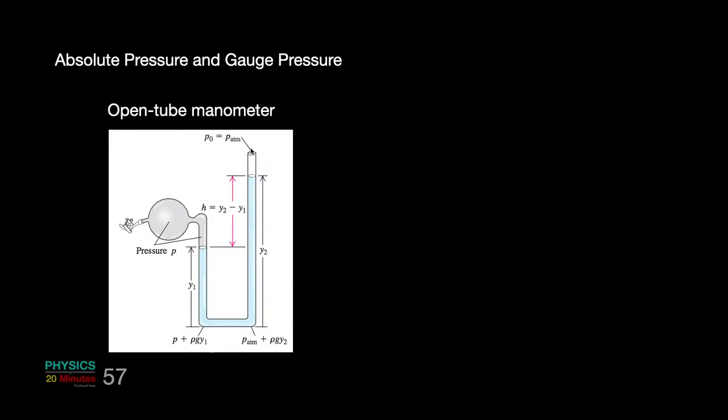One of the simplest things that you can do at home is to just take a long rubber tube you must be having, fill it with water at least half, and then turn it into a U shape and start blowing from one end. If you blow it from one end, the level will go down, and the other side level will go up. Ask someone to measure that height difference, and from that difference you can figure out how much pressure your lungs can apply by way of blowing out. Beautiful fun experiment to do at home.